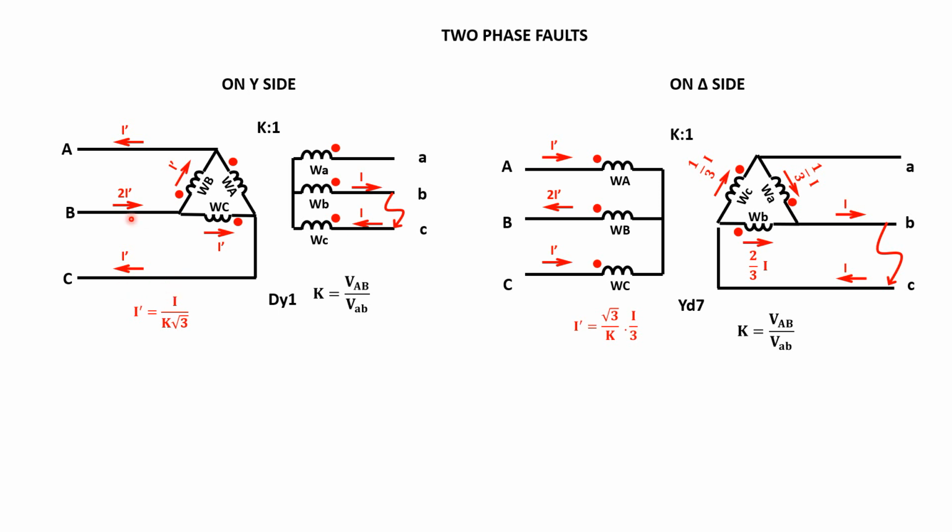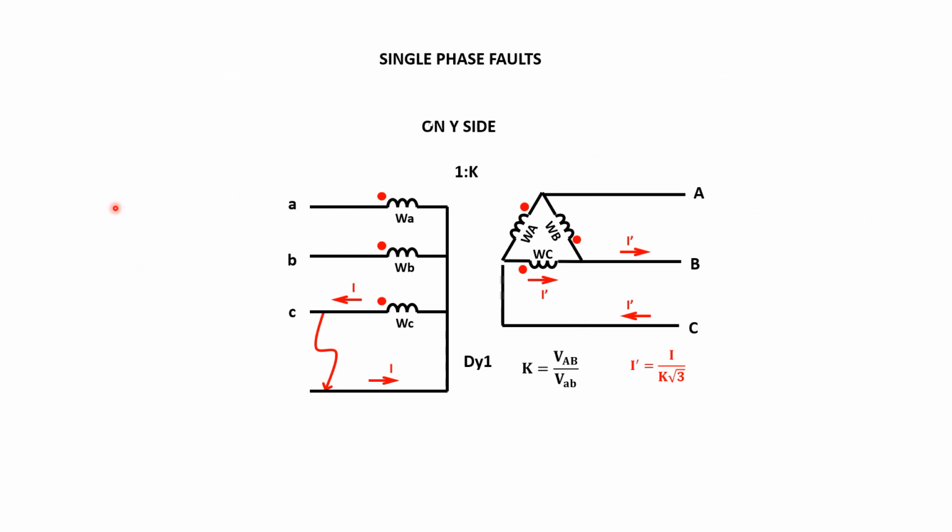This is a typical case: if we have a two-phase fault here, whatever we see in this one, the one phase that sees twice of that sees a three-phase fault, because the two-phase fault current is the square root of 3 divided by 2 of the three-phase fault. The square root of 3 divided by 2 here is basically half of the three-phase current for each of them, and this one sees the full three-phase current, which is important in coordination between curves, not relevant here.